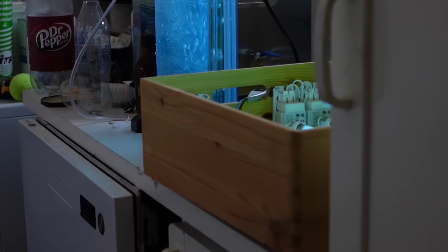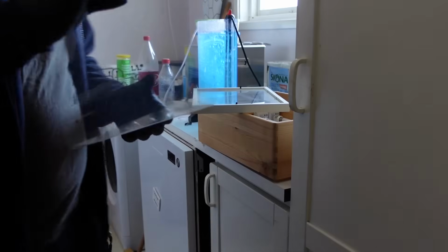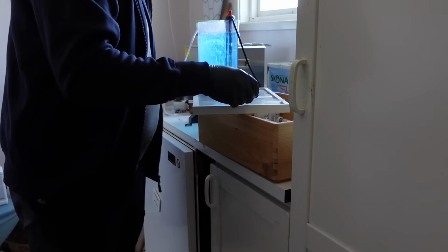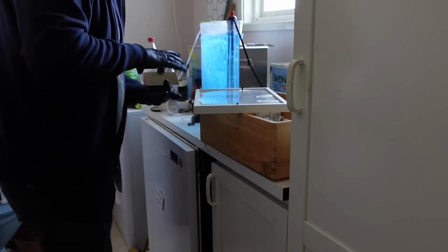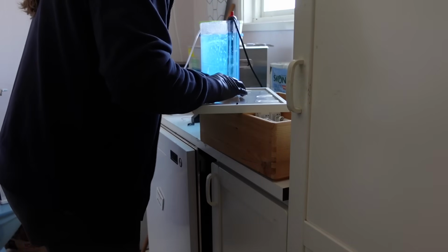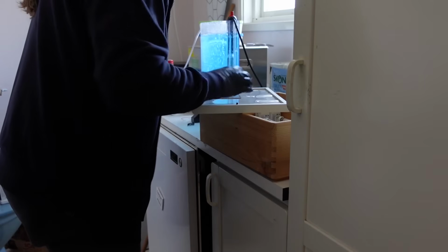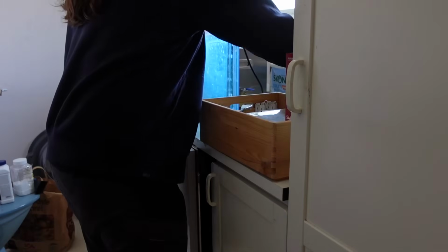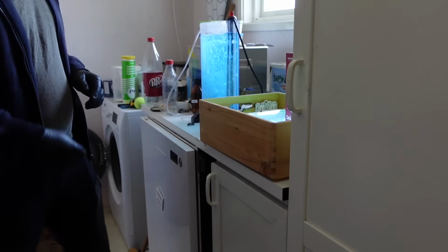These are UVA, so they aren't super dangerous to be around, but we chose not to stand there and stare into them while they were heating up. Next, we can place the film on the glass surface with the toner side up. Next, the protective film over the photoresist on the copper clad was removed and it was placed against the transparency. And then we turned it on for 3.5 minutes.